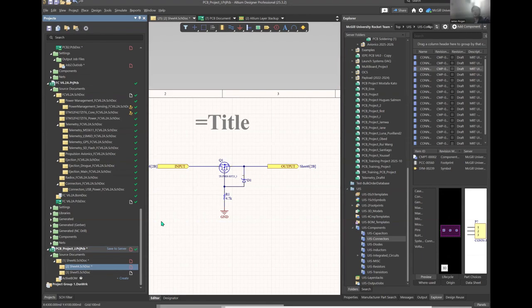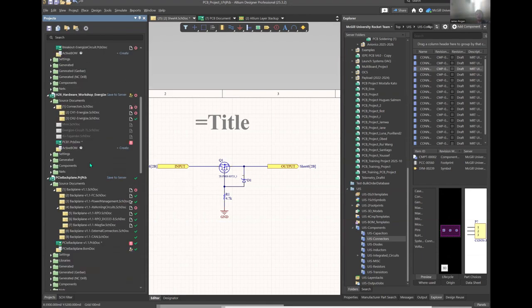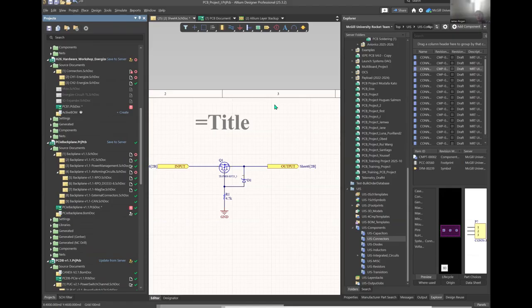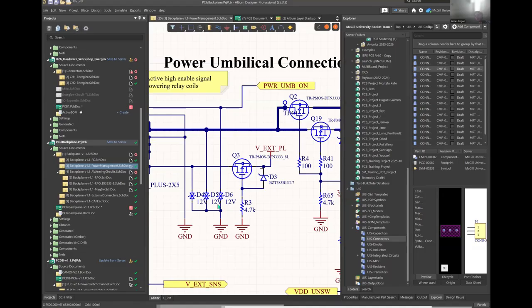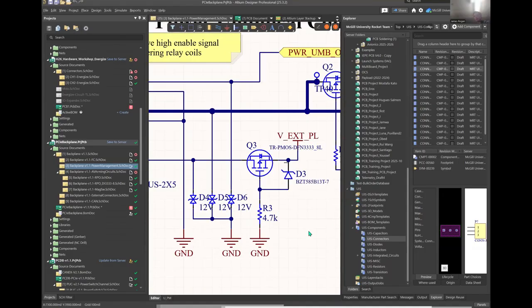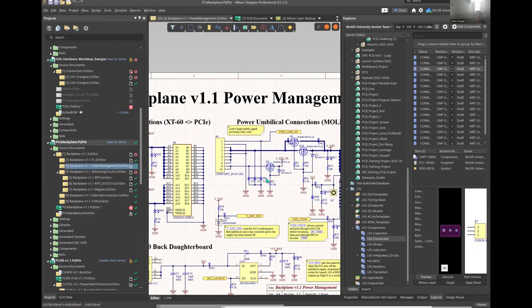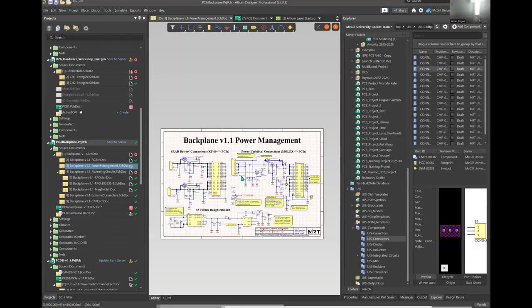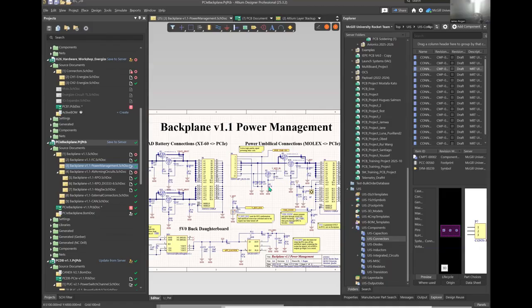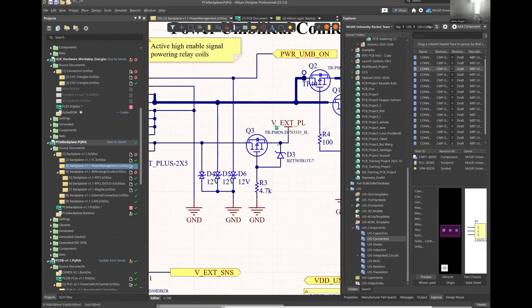Okay, so now I've designed this sub-circuit. I had this sub-circuit drawn because I want to explain that it's used in this broader circuit, which was again using the backplane board as an example. This circuit was used in this part here, where this is reverse polarity protection on this little power path. I want to confirm that this little subcircuit, only 3 components, actually does its job.